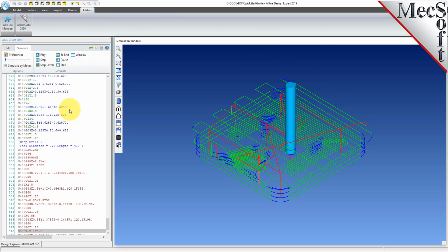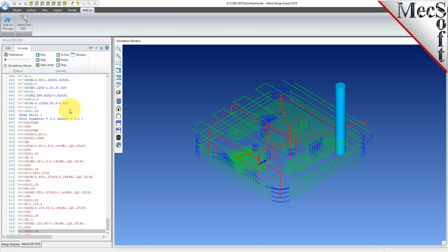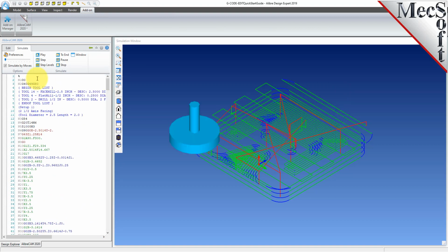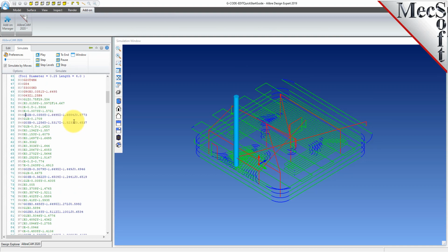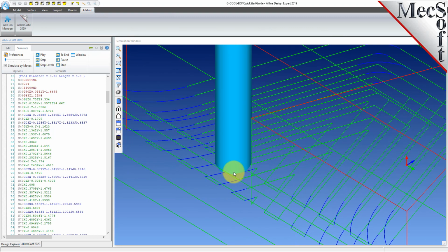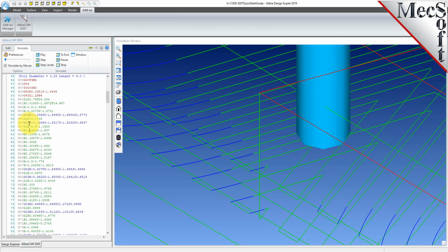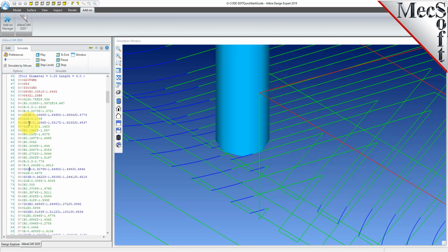And you'll see that the G-code is loaded into the editor, the Simulate tab is activated, and it's running through the G-code file, displaying the correct tool as it goes through each tool motion. Also, which is a cool thing to do, you don't have to run the entire simulation. You can just select a location in the G-code file and use the up and down arrow keys to show where the tool is located at that specific line of G-code. So this is a very good visual analysis, so to speak, of the tool motion itself as it navigates through the G-code file.